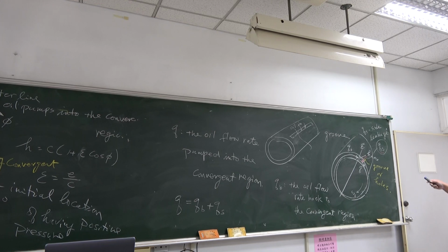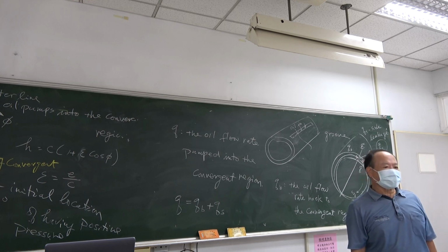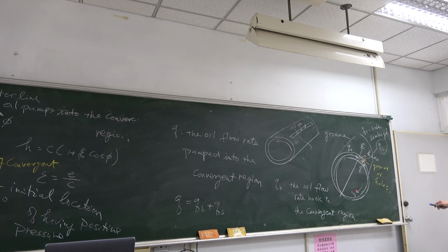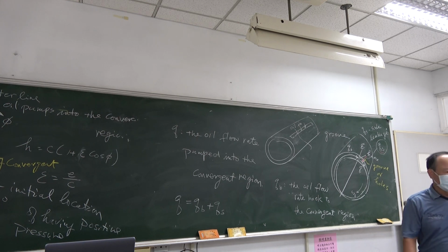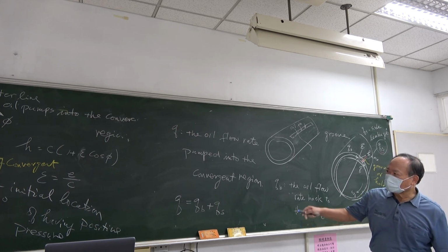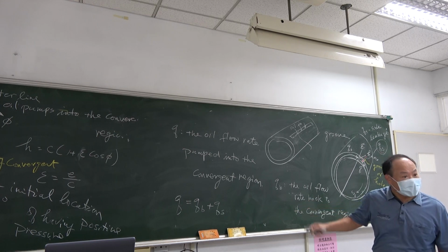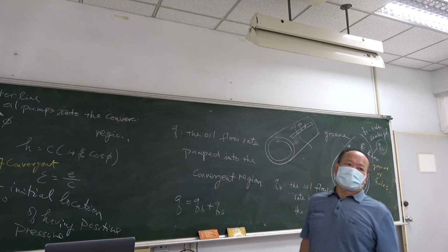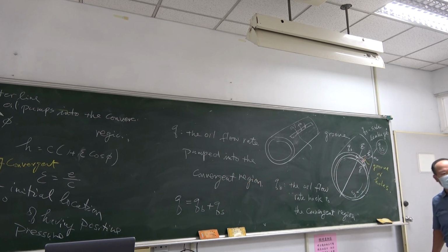If you provide the QS not enough, in the insufficient case, you'll find your positive pressure becomes low. In this case, this pressure cannot support your external applied load. Then your lubrication behavior will go down, your performance will decrease.